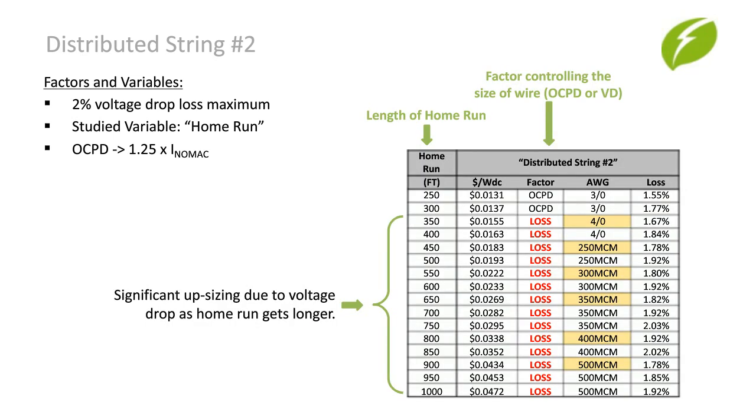The distributed string system wire cost will be from the AC conductors, since our inverters are out in the array field. These inverters have a 600-volt AC output, so they will have about a 20% lower current than you would have if you were using a 480-volt string inverter, which means smaller conductors.